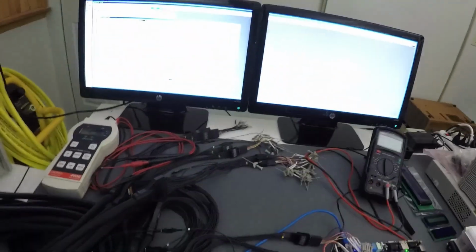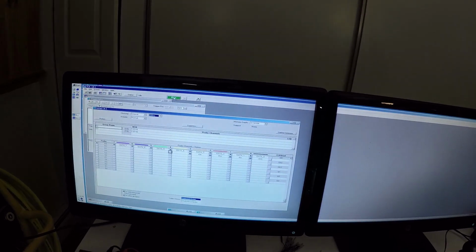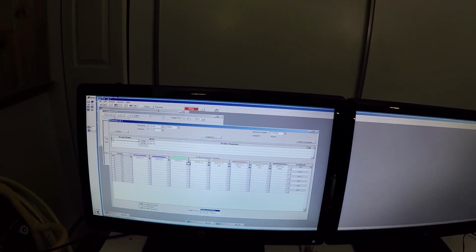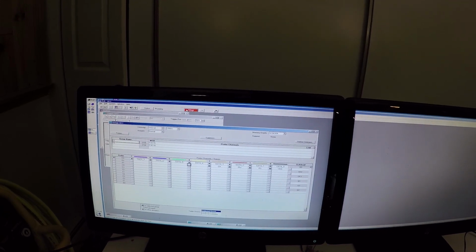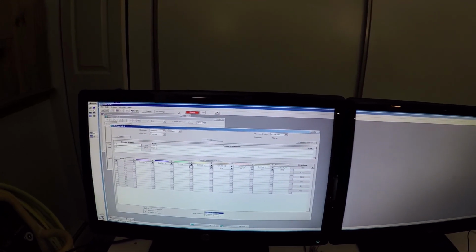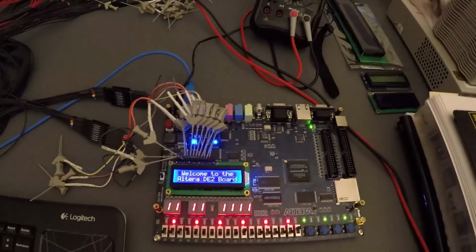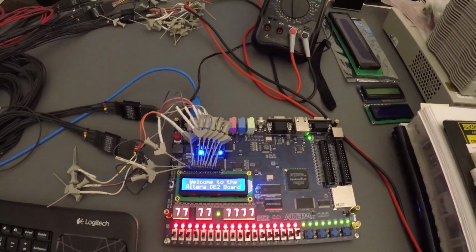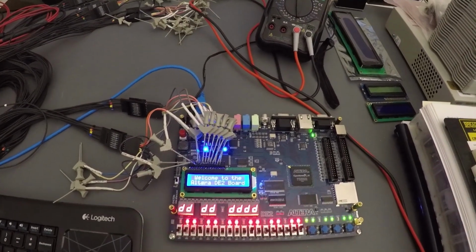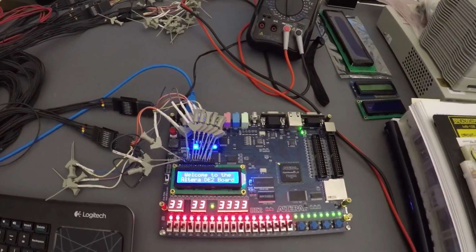So what we're going to do now is actually set up the run sequence for the logic analyzer. So as soon as I hit run here, you can see it's starting. Now it shows here running. So now it says stop because currently it's scanning the 8-bit databus in real time, waiting for that hex value of 38.